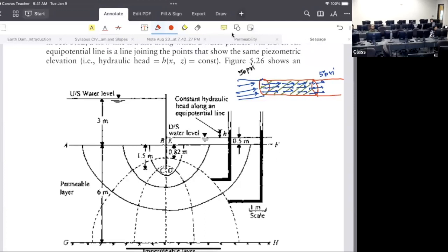But in this case, from the 50 psi, let me try to draw it again. Let's say I'm putting in 50 psi, the pipe has some soil in it, and then we have the water. So when you put in the 50 psi, water just comes up to here, okay? Now, if we increase the water pressure to 100 psi, or let's say 80 psi, what can we expect to happen in this one? Some soil will come out.